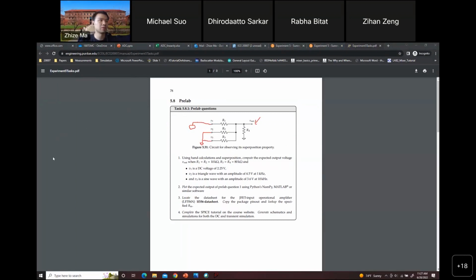Then after you've done this process, for example, you want V2 as your only voltage source, then you need to short V1 and V3 to ground. Okay, sorry, it's not a good drawing, but probably you can understand. V1 and V3 need to be ground when V2 is the only voltage source. So make sure you don't forget this. If you forget to ground the other 2 inputs, you will get the wrong amplitude. Right.